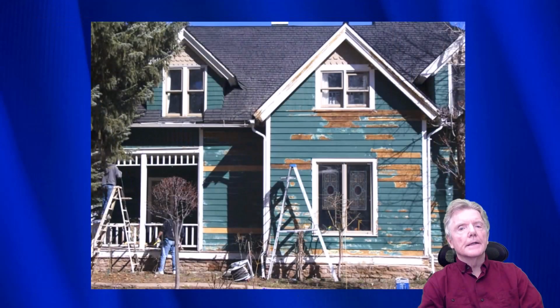Another factor that can cause houses with horizontal wood siding to fail is that at some point in the past 100 years, and we work on houses that are 100 years old, someone didn't paint it. There was some neglect, and the house ended up coming into disrepair. If you don't paint it, then all the nails rust out. And if the nails rust out, it probably goes from 100 pounds per linear foot to only 50 pounds per linear foot, which is clearly insufficient. That's another reason why we probably see the cripple wall failures only occur in houses with horizontal siding.